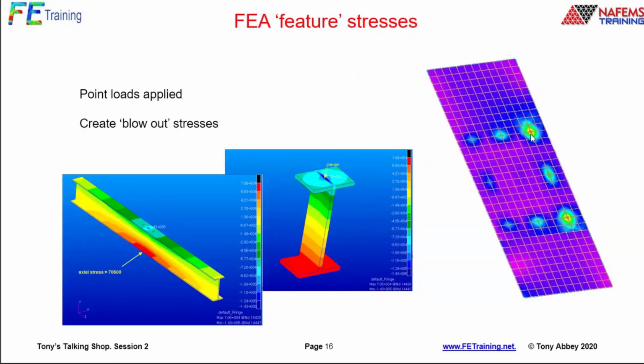Now I can clip the contour back, and I've actually seen a couple of automated processes where the post-processor will clip them back for you. It kind of tries to recognize the singularity and then says, I'm not actually going to show the stresses around the elements around there. I really don't like that. If it's bad news, I want to see the bad news and then fix it up. Or just say, I've set the contour levels myself to deal with that. And again, a methodology explained.